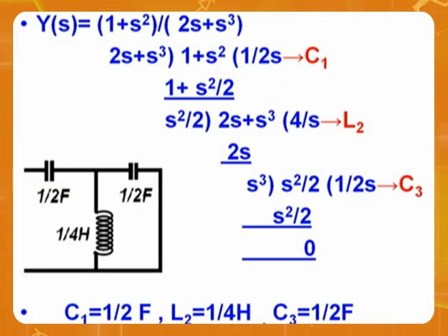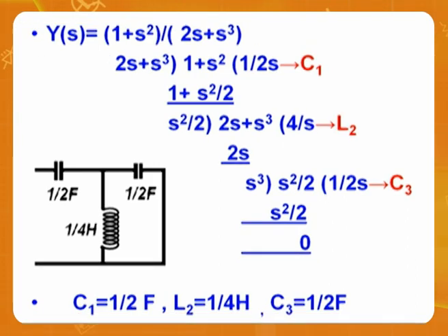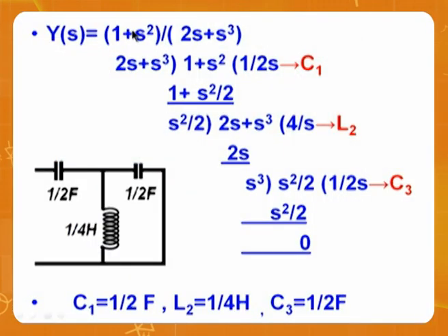Okay. Now continue the solution. Instead of that, I am taking y of s, because that has given me negatives now. As I said, we are all talking about positive real functions. Positive real functions will never achieve negative values. In fact, no component is a negative value, so no negative should occur here. So when z of s is creating a negative, then better go for y of s. Then I have taken the reverse order: numerator became denominator, denominator became numerator.